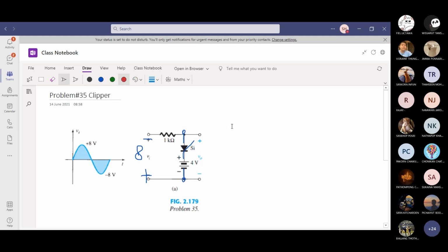Your voltmeter is connected like this. The red probe is the plus probe of the voltmeter, and then you're going to have a black probe, which is the COM or ground. The probe symbol or probe colors is like this. Now, if you ignore the branch in the middle, what will your voltmeter see?